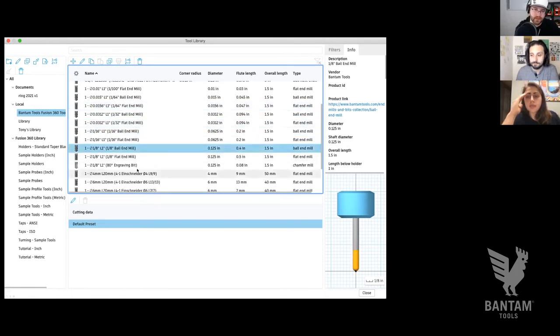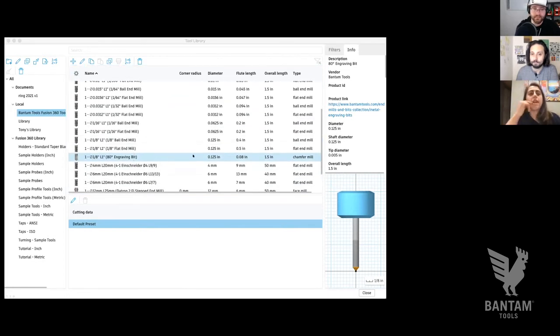I do want to stress a little bit, and this is a whole other conversation we're going to be having in the coming month or so when we start talking more about feeds and speeds. It's a whole ball of wax, and I don't want to get too into it right now. But I just want to point out, Tony, that the default feeds and speeds that we have here are actually pretty conservative for aluminum, so we'll be modifying those when we start creating our tool paths. Even for the PCB mill, these are pretty conservative, I think. Yes, they are. So for our CNC machine, we're going at 50% right now. That's what the defaults are at, I think.